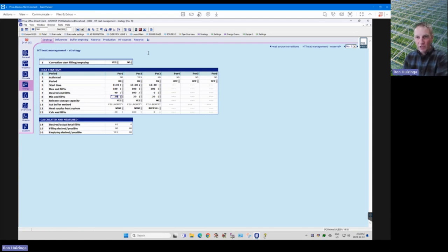So yeah, then I would say that's a cold front. So as big as a 15-degree temperature difference, or vice versa. Maybe it's minus 10 for the last couple of days, and all of a sudden the forecast for this evening shows a warm front coming through, and it's going to be plus 5 degrees. So a 15-degree difference or so. Yeah, a 5-degree difference, 10-degree difference is probably not a problem for the buffer tank. But when you start getting a 15 Celsius difference, then that's going to be a big difference for the heat demand.